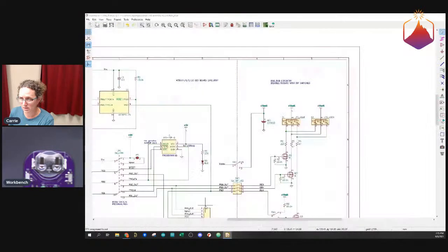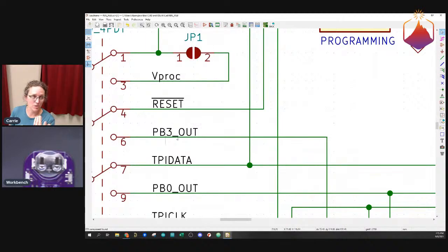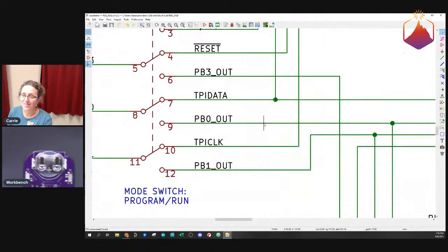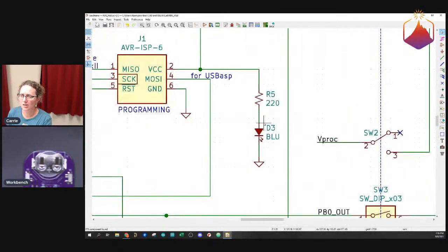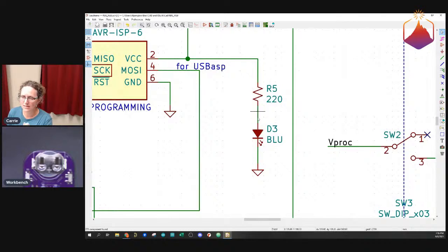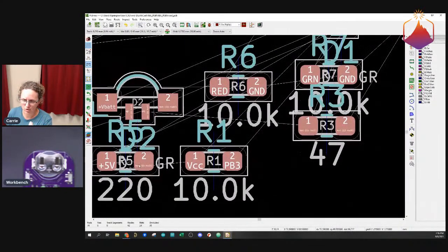So when we go back to the schematic here, these are all of these labels. So I've named these nets. For nets that I have not named, because it's not important to name them all, that gets visually cluttered. Like this net right here that connects the resistor to the LED is not named. It automatically generated net names for those. So it's like net D3 pad 2, right?